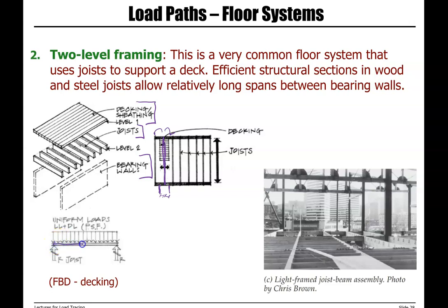So first we do a free body diagram for our decking. Again, the load is in PSF. The reactions are transferred to the joist. So each one transfers a load to the joist.